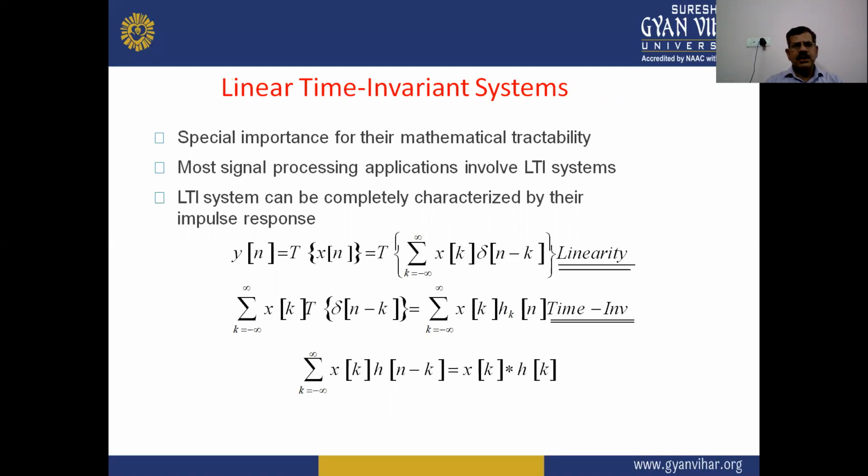Next one is the linear time invariant, LTI, system. LTI systems have special importance for their mathematical tractability. Most signal processing applications involve LTI systems. An LTI system can be completely characterized by its impulse response.